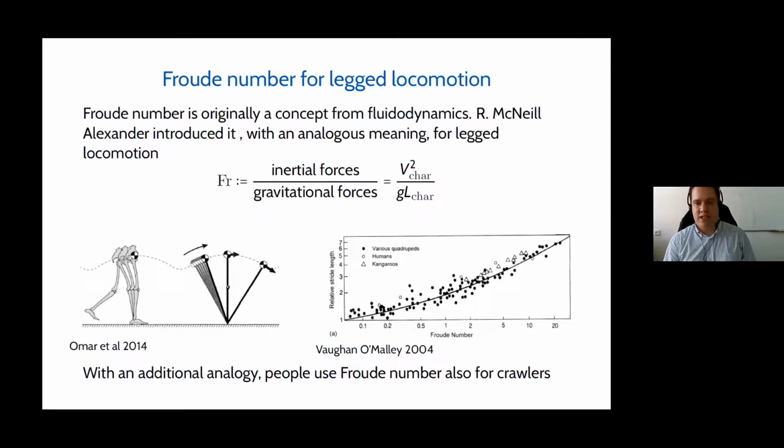How can you say if an animal is walking or running? Usually you can identify them by looking at how relevant inertial forces are. This is quite useful. For instance, the classical problem of the first walking robots: they walk really, really slowly, and they are essentially quasi-static. You can compute their Froude number, and it is very, very small.